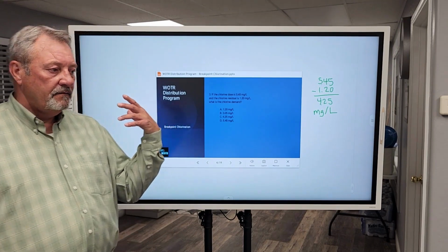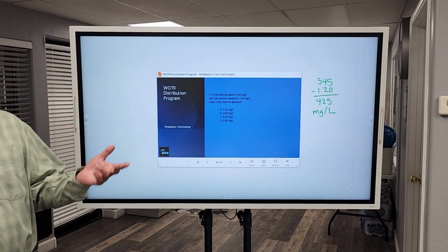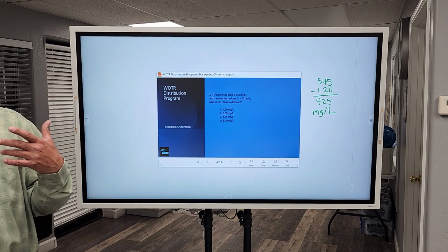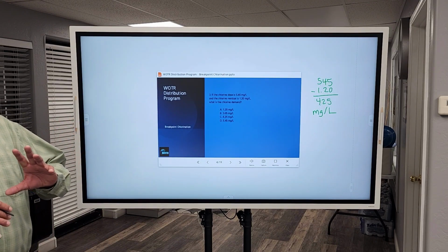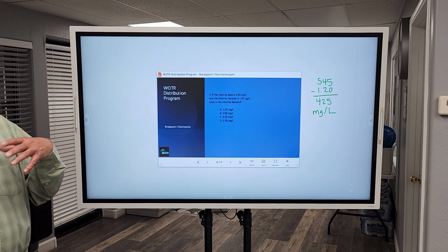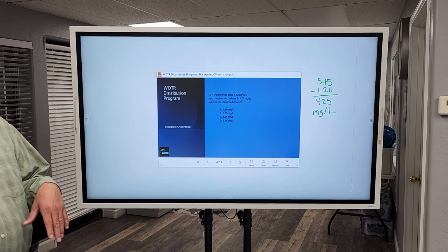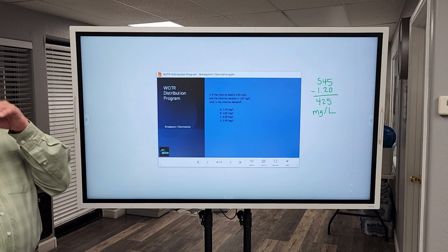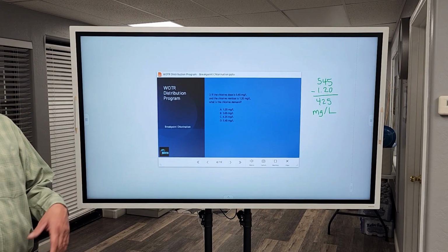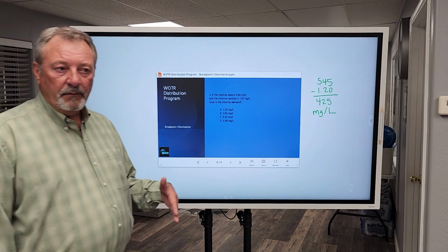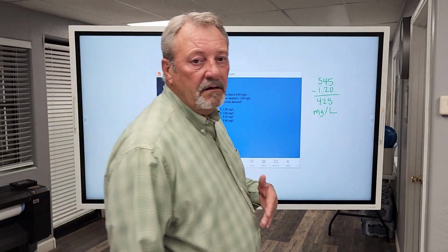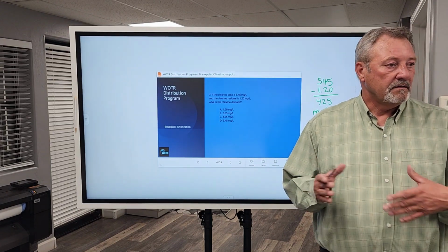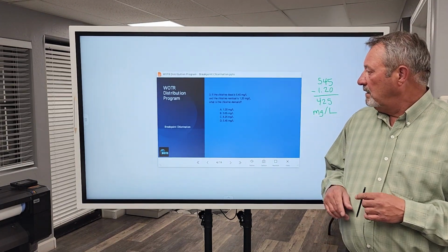You're going to have bacteria, viruses. You're going to have fecal matter, all that stuff that gets found in the water, in the lake, at the river, things like that. It's all going to be in the water. So the surface water treatment plant is designed to first screen off a bunch of that stuff, but also settle it out, and then send the water through filtration all the way to disinfection.